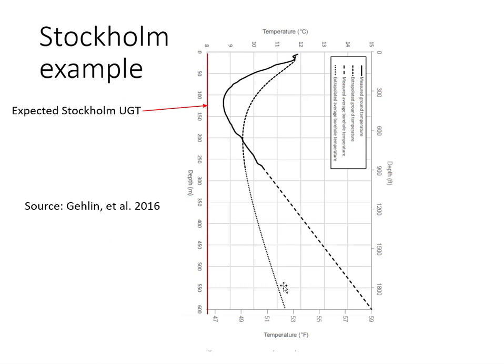If you ignore this line here, this would be the average temperature over the borehole depth given the temperature variation. This is the actual measured temperatures here down to almost 900 feet, so it's quite deep. The red line here is about what we would expect for the Stockholm undisturbed ground temperature. And this part here is what we see as the effect of urbanization. And then down here, you see that sort of straight line. This is what we call the geothermal gradient.